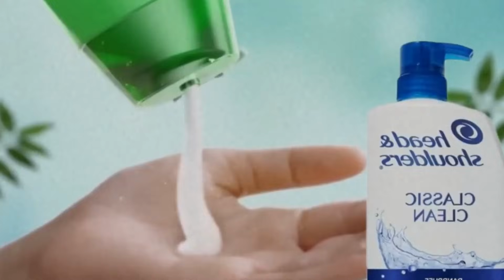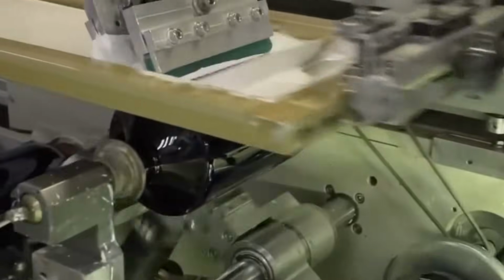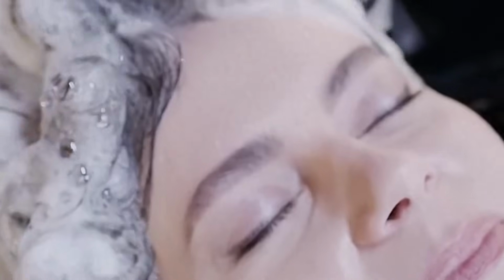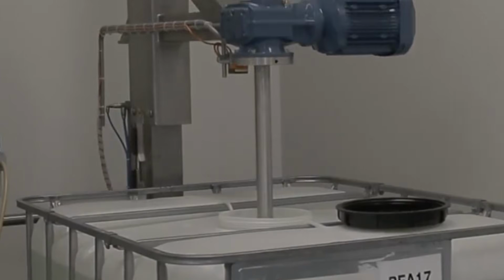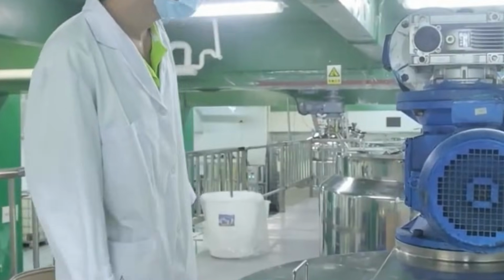Shampoo production begins with the preparation of process water, which functions as the primary carrier for all ingredients. Incoming water is treated through multi-stage filtration systems that include sand filtration, activated carbon beds, reverse osmosis membranes, and ultraviolet sterilization. Treated water is stored in stainless steel buffer tanks equipped with recirculation pumps to maintain uniform temperature and prevent stratification. The manufacturing process is typically batch-based, although some high-volume lines use semi-continuous systems.